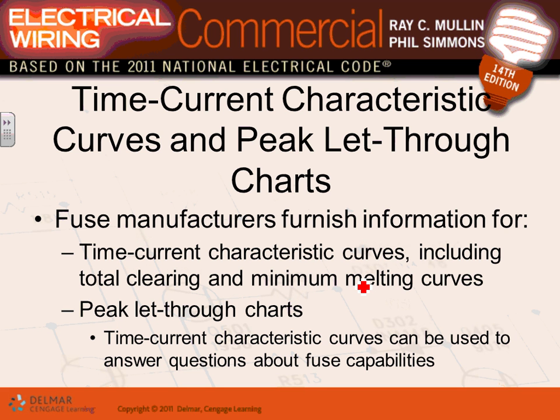Time current characteristic curves and peak let-through curves. These are all the curves that we use, guys. There's something called time current characteristic curves. We're going to be doing this one next week, guys. You're going to be looking at these. Every circuit breaker has a time current characteristic curve, meaning the larger the short circuit or ground fault, the faster the fuse or the circuit breaker will trip.